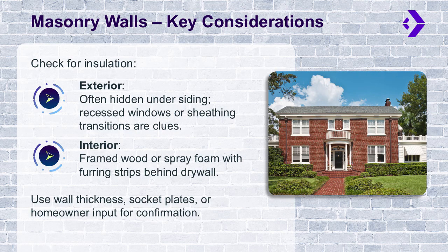For masonry walls, we're going to look for insulation on the outside and the inside of the masonry. For above grade masonry walls, they're almost always going to be insulated somewhere. Never assume zero insulation. You'd be able to feel the cold through such a wall easily.